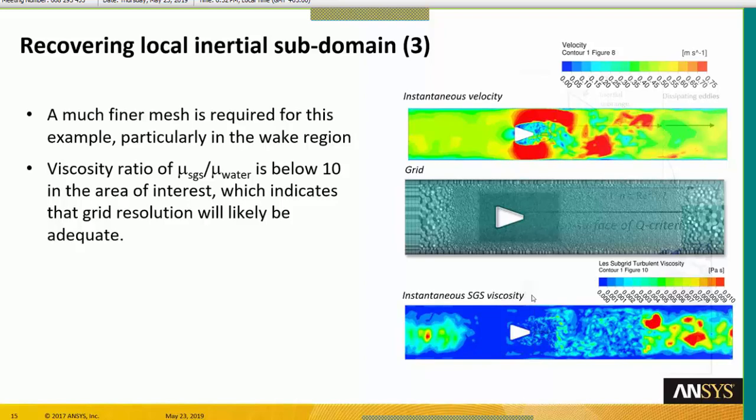And that translates exactly on the subgrid scale viscosity level. You see that now you are clearly well below this value of 10, regarding the ratio between the subgrid scale viscosity and the dynamic viscosity of your fluid. So this is a good indicator, things are getting better. So let's start to have a look at the dissipation spectrum.